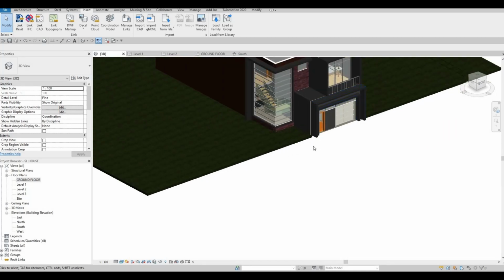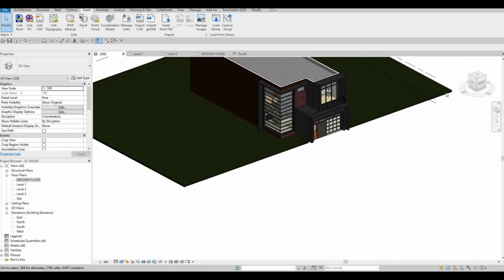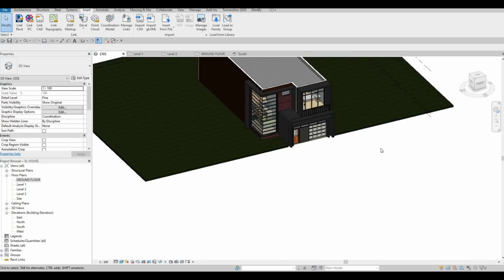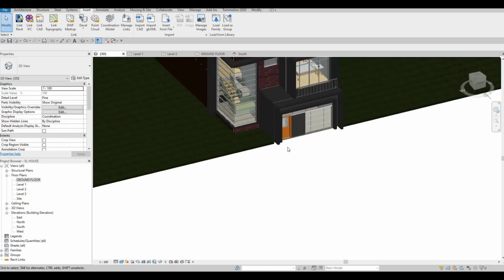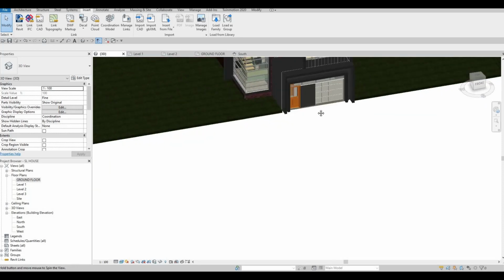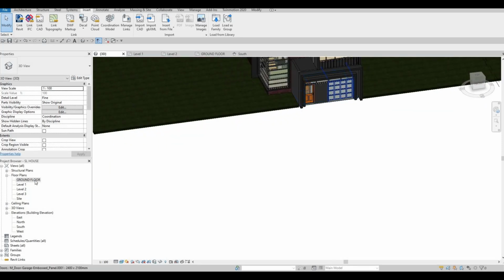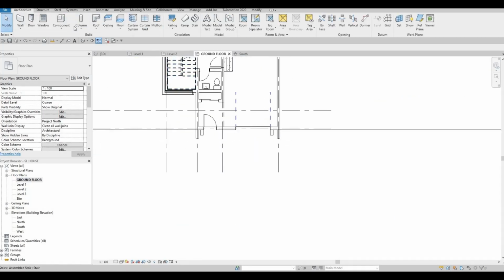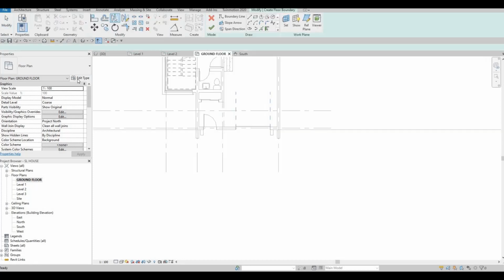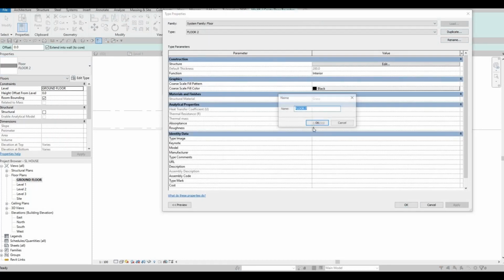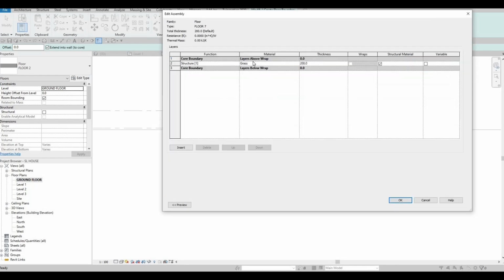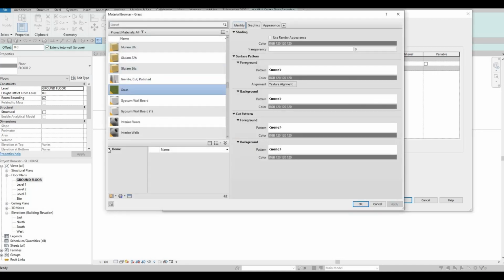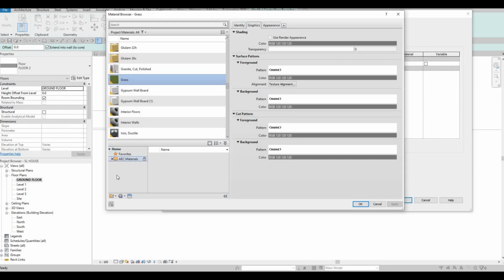One thing we need to add is some separation here from the outside. So what I'm planning to do is I'm gonna add in something, so a floor here. I'm still going to add another floor, so click on floor, edit type, duplicate, floor number 7, edit. This will be one of the concrete floors. So let's add a concrete floor right here,